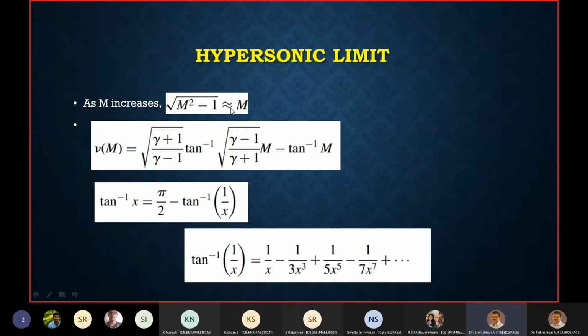So in both terms it can be taken as M. Now when you substitute it back, the expression becomes nu of M equals gamma, square root of gamma plus 1 by gamma minus 1, multiplied by tan inverse of square root of gamma minus 1 by gamma plus 1 multiplied by M, minus tan inverse M. Instead of the square root of M squared minus 1, it just becomes tan inverse M.